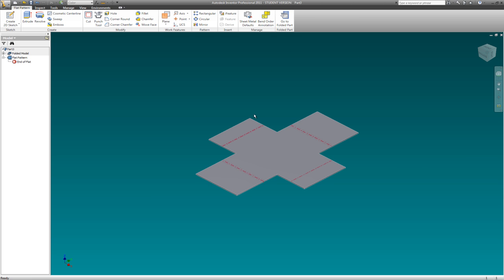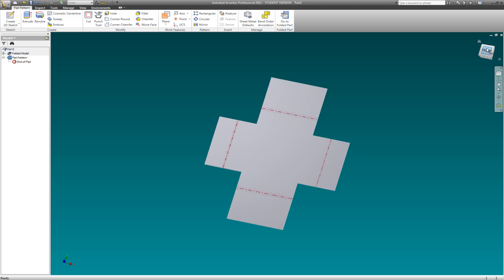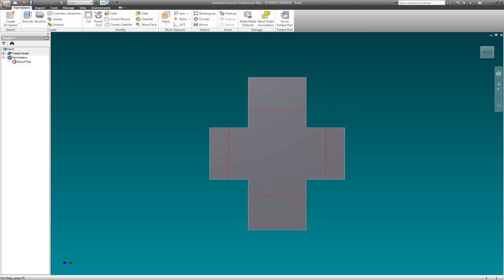to make it flat. And one of the things that's kind of interesting about that is if I go in here and do some dimensioning, you're going to see some pretty unique dimensions. Yeah, 875, and then we got here. Okay, and that one is 6989. That has to do with this K factor thing. And even though the dimensions that you knew was 5 across, and in this case 1 inch up, so that should be a total of 7 inches. It is not 7 inches, it's short that.